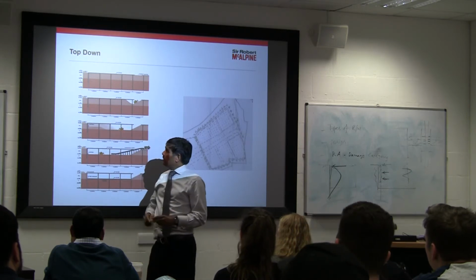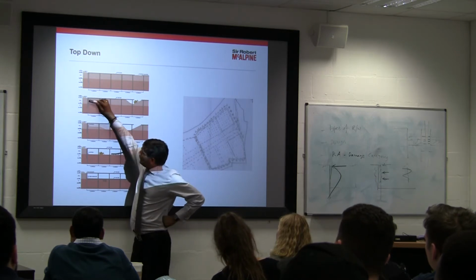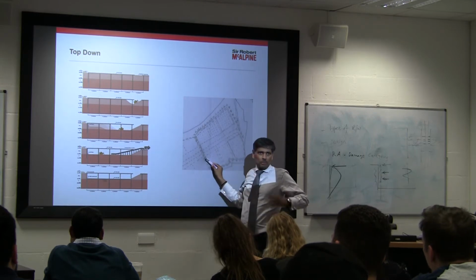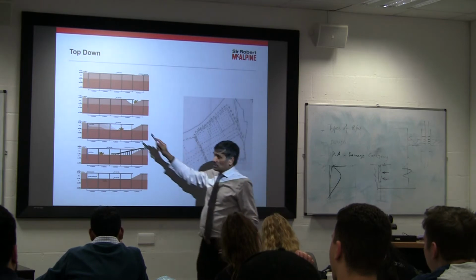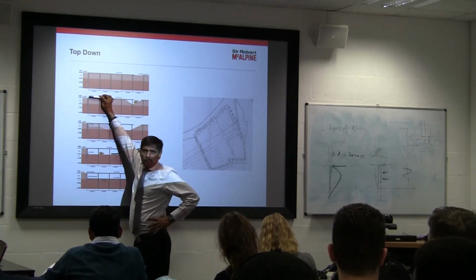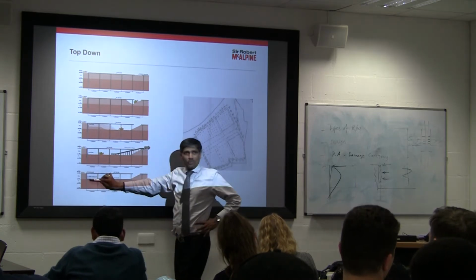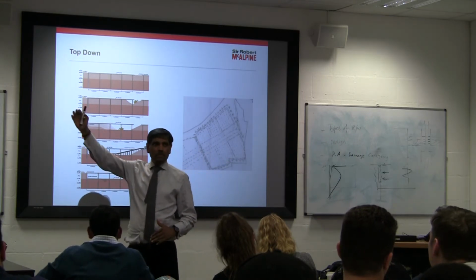Yes. The reason is we already locked in at the ground, so the wall cannot go anywhere. So the perimeter wall that you have done, this is the perimeter wall I talked about, secant, sheet pile, whatever you choose depending upon the ground. In this case, because we are locking regularly, we lock that on the deck, we excavate it, we lock it again. So we got the second floor. So it's nicely held up at every level. So it's actually spanning between the floors.